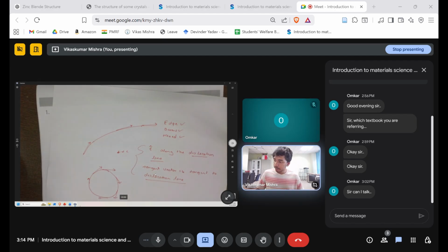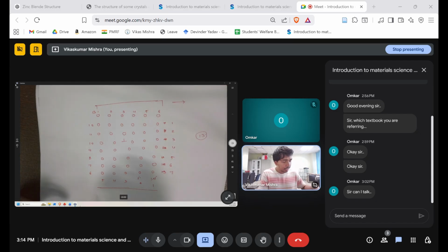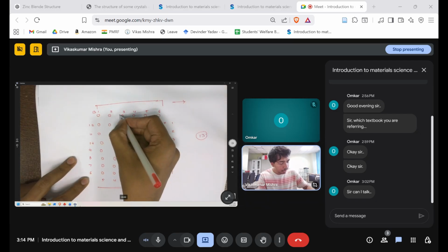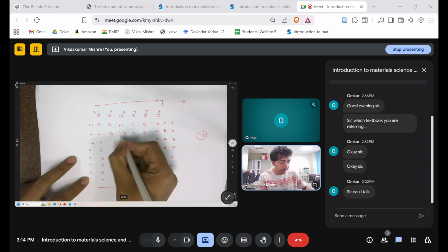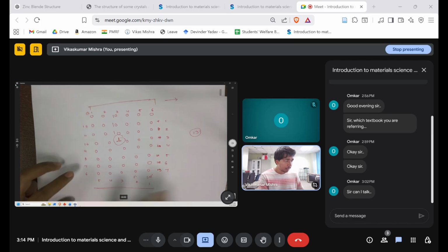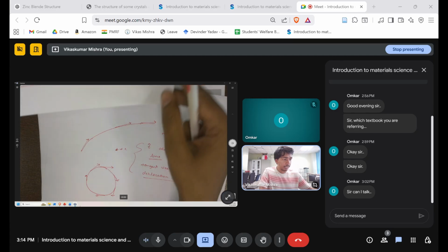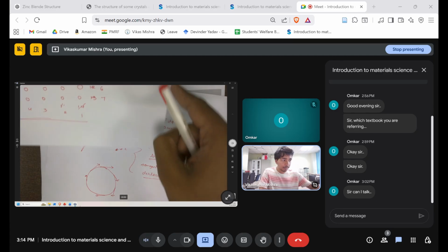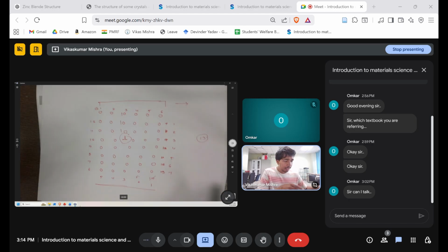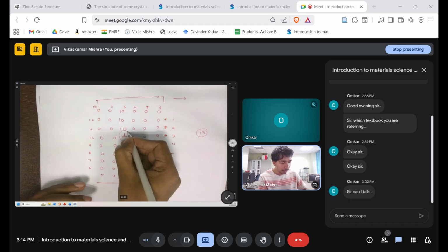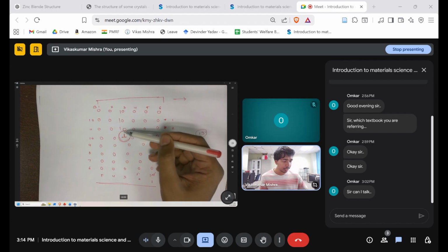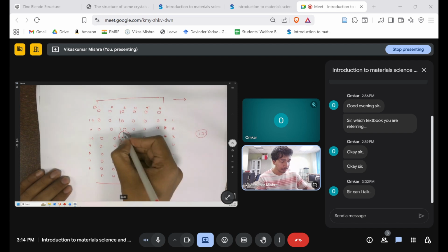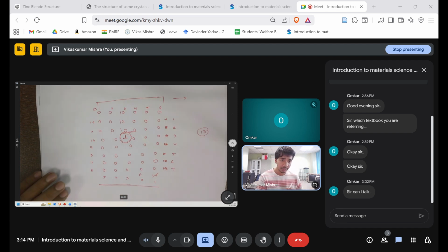At this location, we can see an extra edge over here. The atom was present here, and suddenly we see there is no atom. So what we are seeing is like an edge. Nothing is there just below it, right? We call this also an edge. After this particular point, there is no atom along this particular plane, this particular paper. So it is an edge, and just below that, we call it the edge dislocation. Screw makes the screw, and edge dislocation is just below the atom. We see that below the atom there is nothing, so it's like an edge. An edge has been created at this particular point, so we call it the edge dislocation.